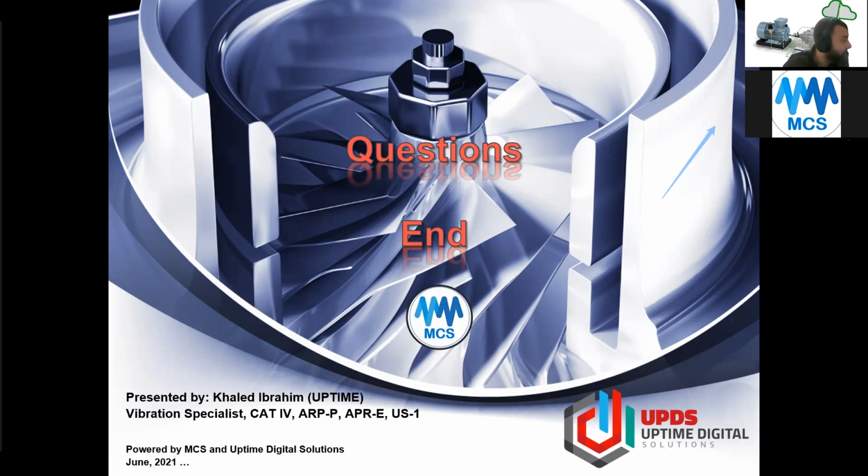Another question: how to assign X and Y probe locations on the gearboxes? Or let's rephrase your question: how can we make the provision? Most probably you don't have the upper hand on the provision, except if you are running a brown field machine, an old machine that you would like to install on. Most probably we follow the convention for naming and location if you have full accessibility for the XY probes. So you take the 0 from the top, from the vertical, and you go 45 degrees positive and 45 degrees negative, if you have the room. If not, you need to consult with your OEM.